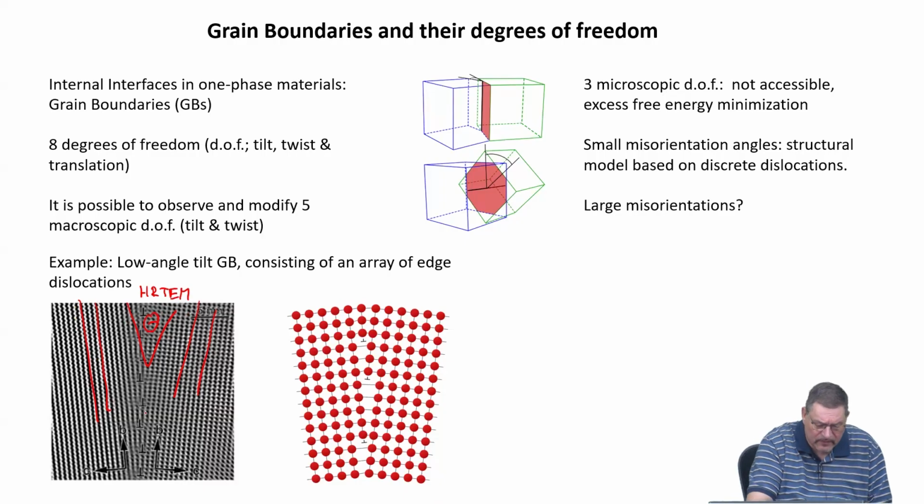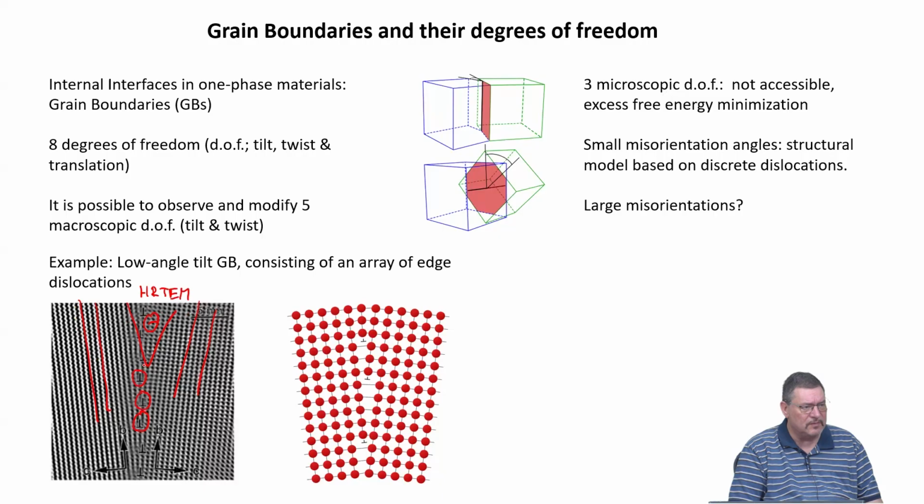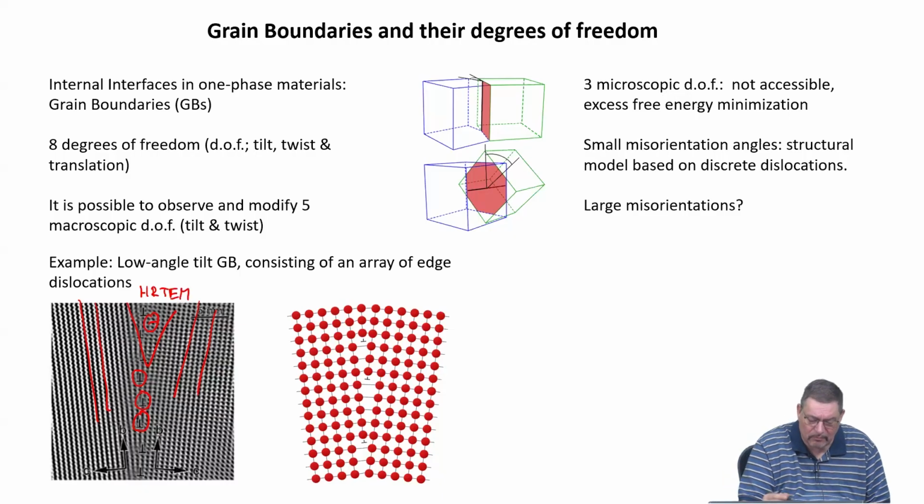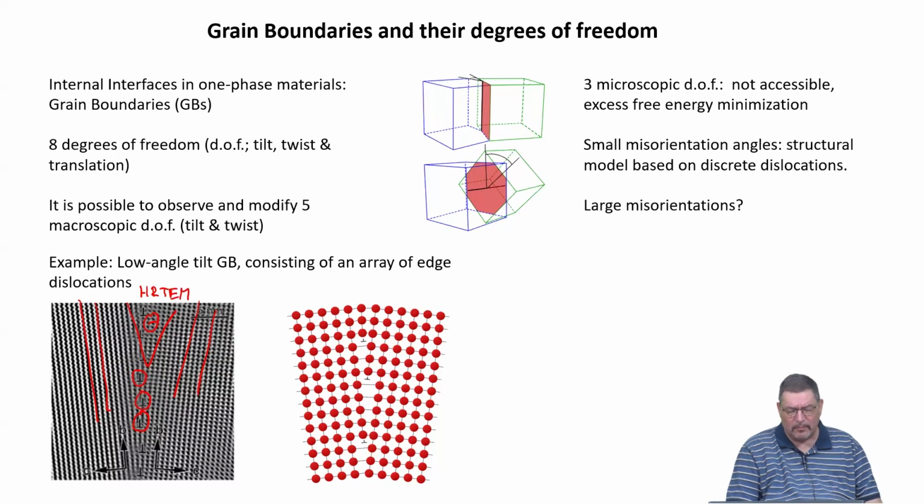You also see these funny symbols. They are the dislocations which have basically been aligned. They have not been aligned, they align themselves because that minimizes the total energy stored in their strain field. This is why if you have many dislocations, you get cell formation, low angle grain boundary formation. And the nice picture replacing atom columns by balls in red is given here.